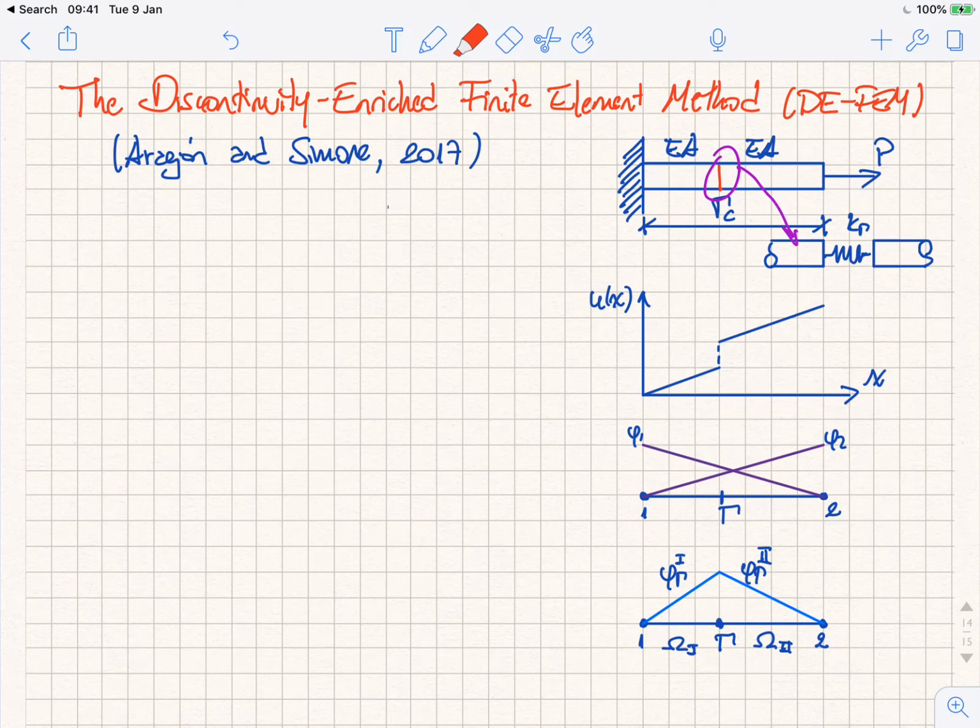Yeah. So who remembers what is the displacement due to the deformation of the bar? Someone remembers that? P times L divided by, no one? Divided by EA. Yes. PL divided by EA is the deformation of the bar, plus the deformation in the spring, simpler. P over K. Very good. Yeah. So that would be the total deformation that you have at the right tip.